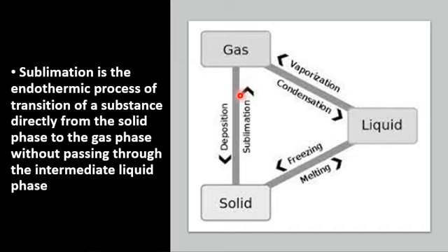When the solid is converted into a gas form, the sublimation is done. Then the gaseous material is deposited onto the surface of the substrate, and it is condensed onto the surface of this substrate, forming a deposited thin film.